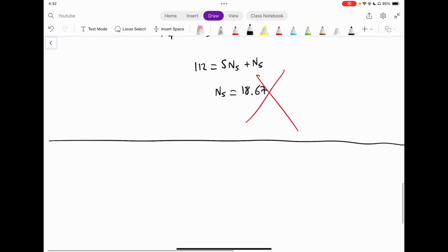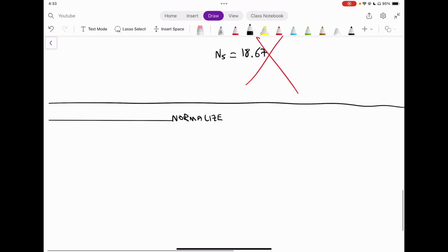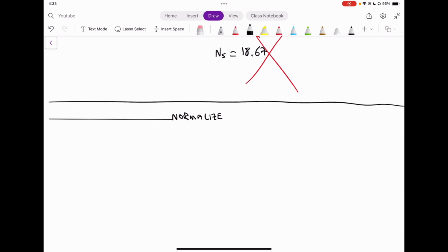So if we look at our system and our problem again, we're going to normalize our values. What we're going to do is what we did previously in the problem: let's go back to square one and assume, even though we already know that one gear tooth wouldn't work because we have interference and we need 16 minimum, that N3 is going to be equal to 1, okay?